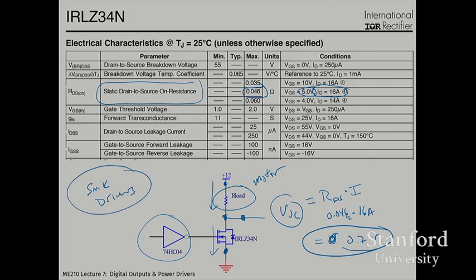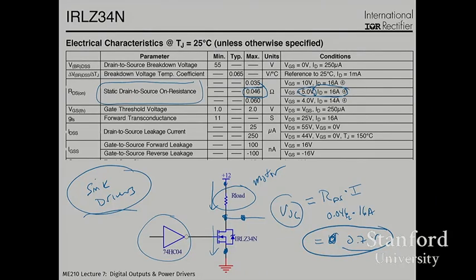Now there is a complementary family of parts called source drivers. They just have the other kind of MOSFET or the other kind of bipolar junction transistor. And the configuration from the standpoint of connections to power and ground is inverted. In the on state, the output is a high state relative to ground. There may be instances where that's the right configuration for the logic and devices you want to operate. I will tell you flat out, though, that the vast majority of devices in this product category are going to be of the sink driving type. That's just because this is the way this community started, and there's a presumption of design for sink drivers rather than source drivers.